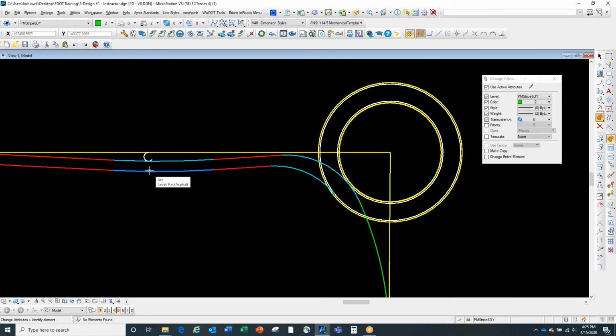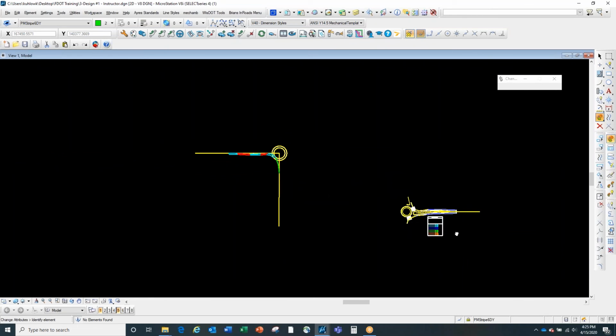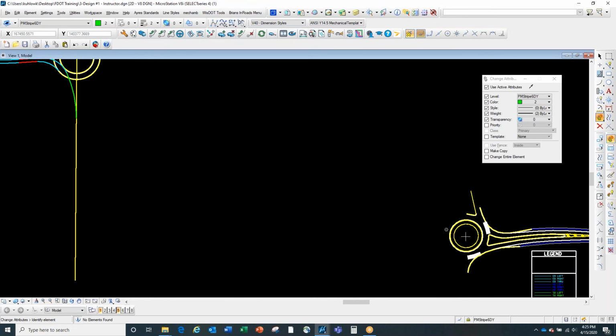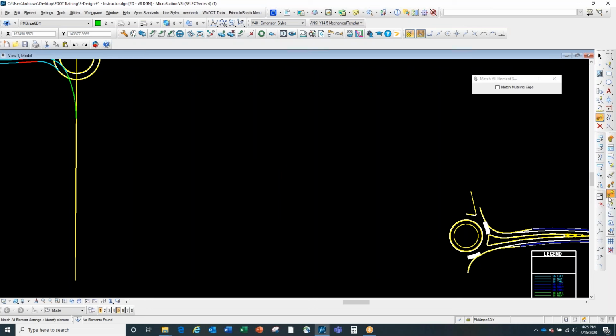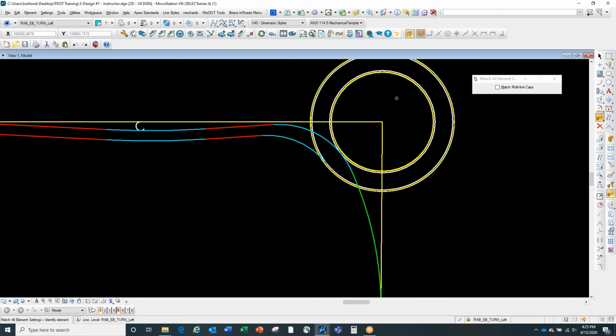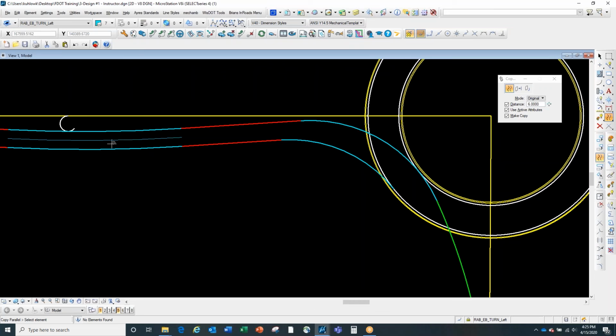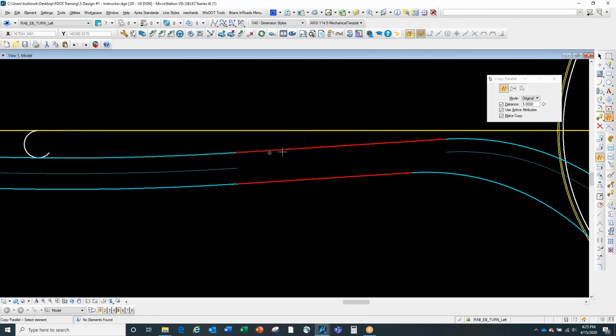All right, so now let's go ahead and check our truck, and this is going to be an eastbound left. So I'll go ahead and get that on the right level here. As they're approaching the roundabout, a lot of times I'll center them if the radiuses are large enough. So there's 6 feet there. We'll do 5 feet off here, and we'll just do 5 feet out the exit as well.